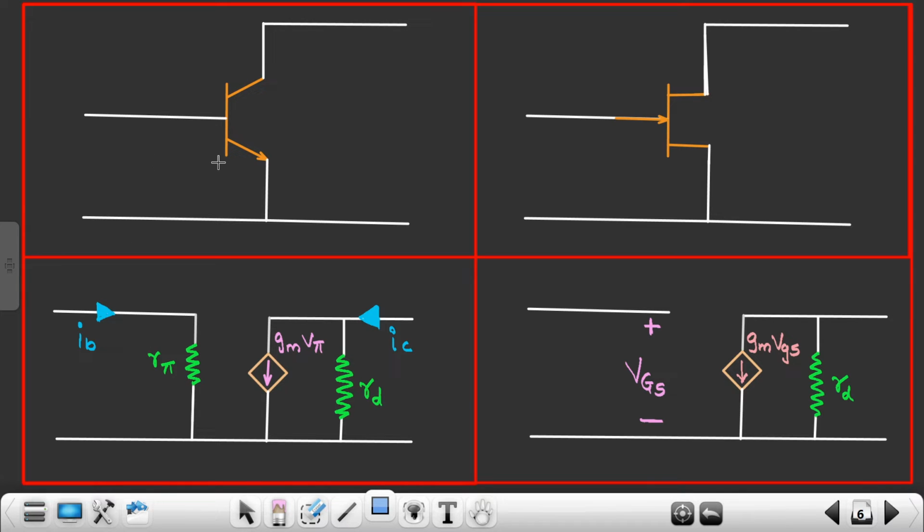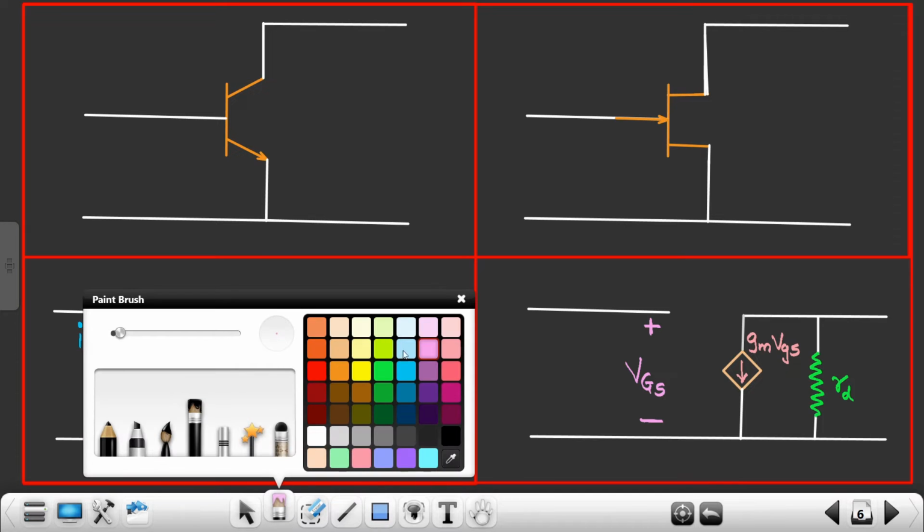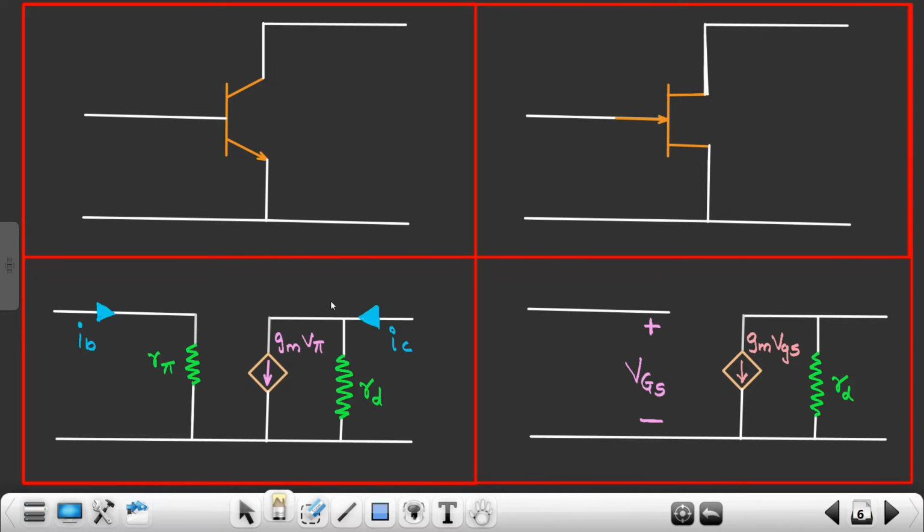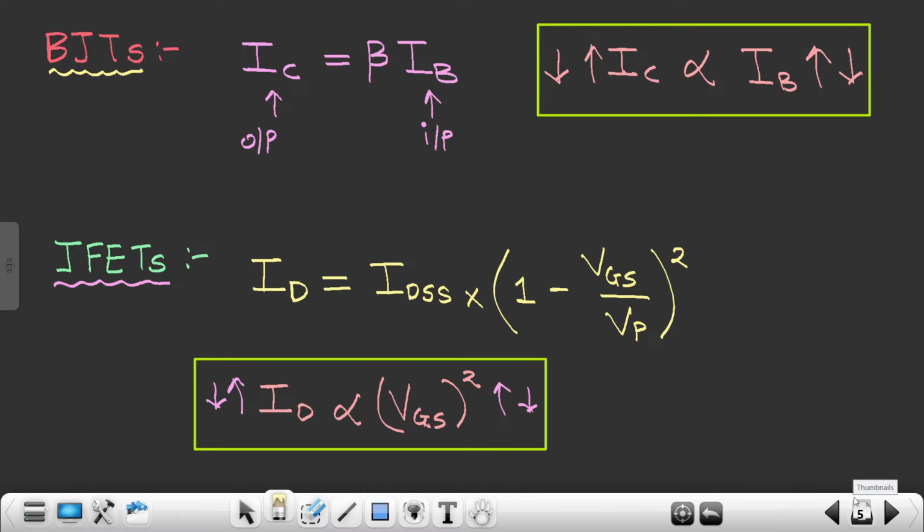See, this is my BJT, this is my JFET, and this is how it is represented symbol wise, right? So for BJT, the terminals involved are base, collector, and this is emitter. Okay, obviously if we are dealing with CE amplifier or rather CE configuration. When it comes to JFET, if we are dealing with common source configuration, so this is gate, right? This is source and this is drain. Okay, and just now we saw that our input current is actually controlling the output current.